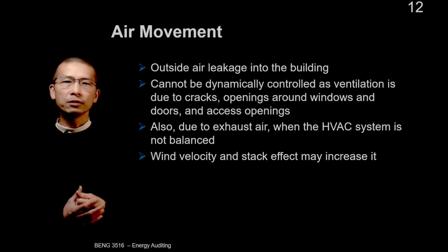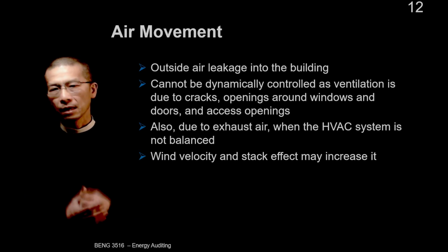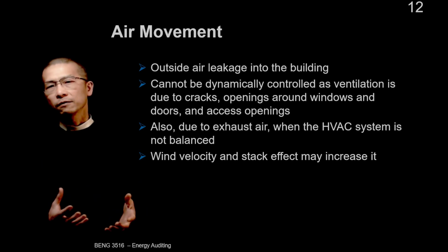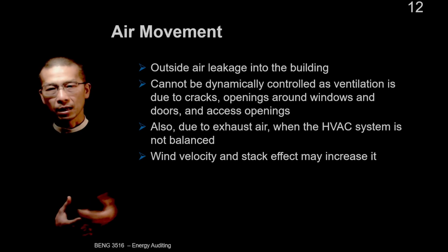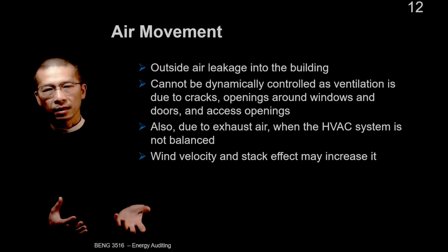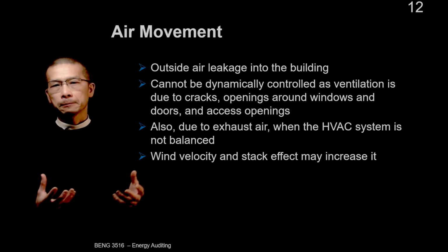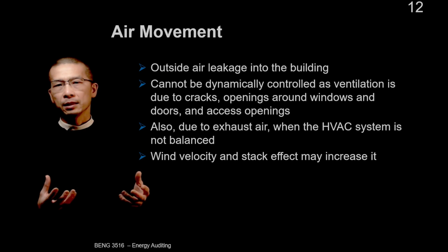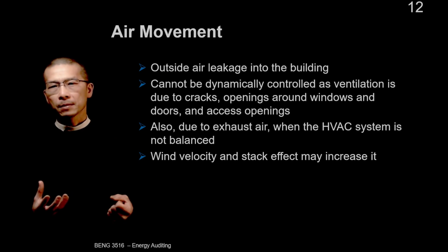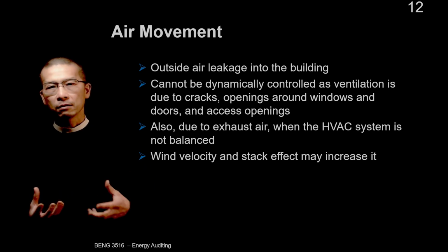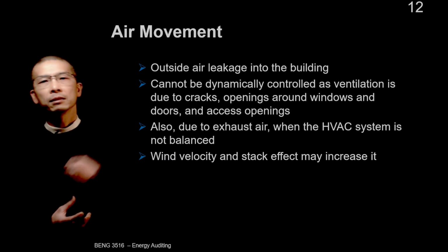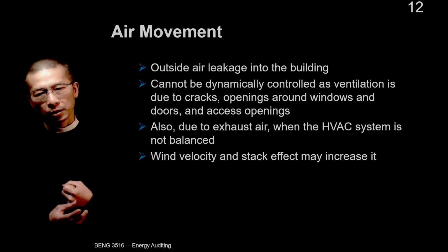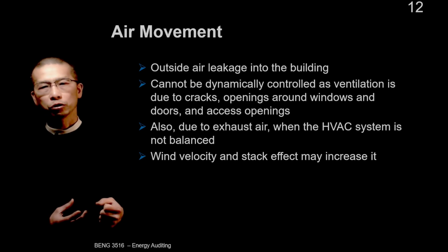We also have to look at the HVAC balance. If a building's exhaust fans are pulling out more air than the supply fans are supplying, the building will fall into negative pressure, because you're drawing more air out of the building.